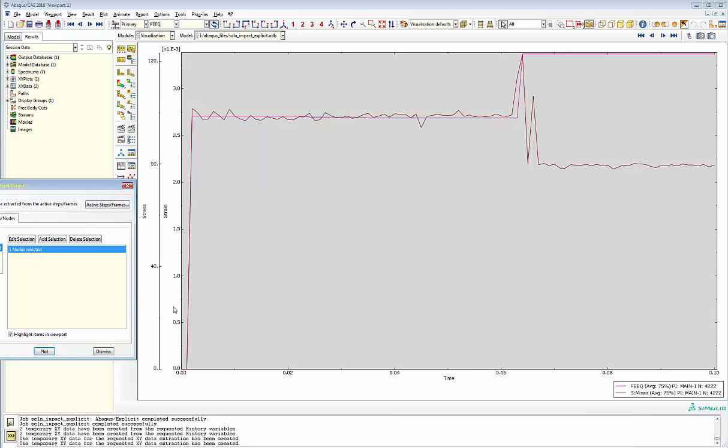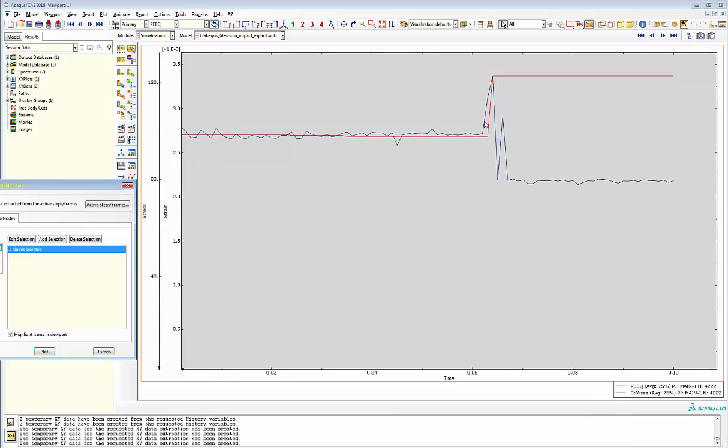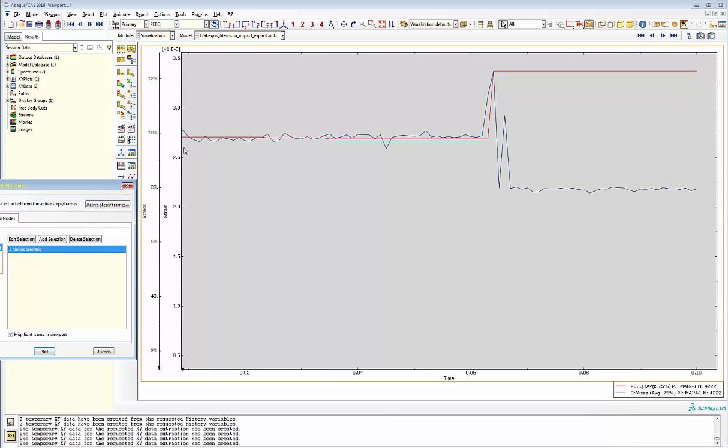You will see that if I were to zoom back out a little bit of this plot, the stress is the one that is in red. I'm going to replot that so colors will be a little bit more distinct. Yes, that's much better. The stresses are now plotted in blue, and the plastic strain is plotted in red. You notice that because of some secondary change in the value of the stress, the strain also has gone up accordingly. Although this may be looking ominous, you notice the change is not really all that much so far as the plastic strain is concerned.